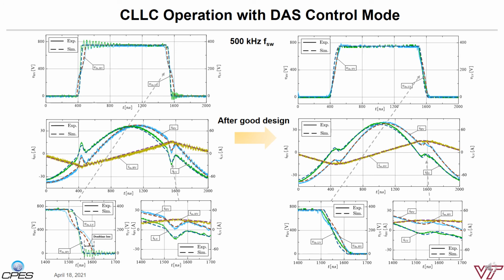Therefore, additional dead time losses are created. The current also shows large readings during the dead time period. In addition, there are high-frequency voltage readings created on top of the devices, leading to high EMI noise and voltage stress. However, on the right-hand side, it shows the optimal device voltage transition performance during the dead time.